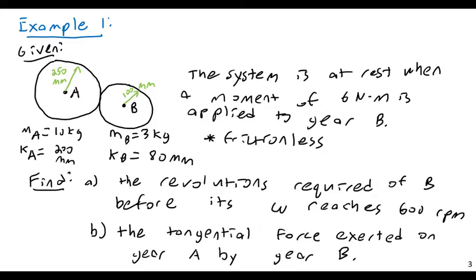But the downside is those gears must be able to take that force. In other words, if you have a tooth gear type thing like this, and the other one coming in like this to meet it, well, this is just one metal surface bearing against another metal surface. And the forces here will want to cause one set of teeth to shear the other set of teeth off.